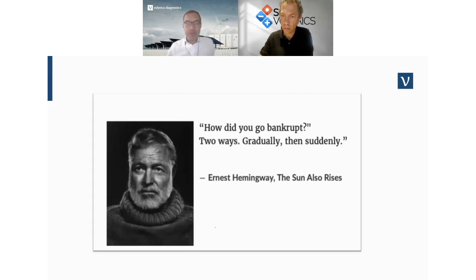But unfortunately, we now skip the availability part for time reasons, and LFP systems, if you don't monitor them well, tend to have more availability problems due to their flat OCV curve, for the nerds among you, than NMC. NMC are typically better to manage. So if you want a high availability and low degradation, it's a difficult thing, because with LFP, availability issues maybe. Right. Okay.